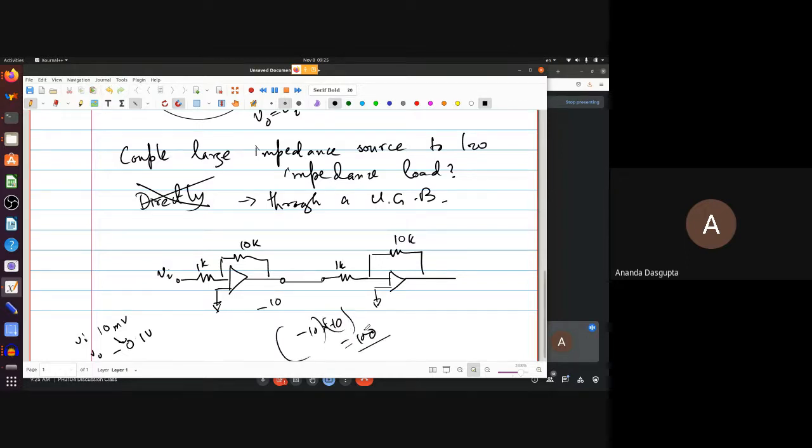Now, this kind of coupling we have to do over and over again various times. The only problem with doing this coupling directly is that the input impedance to this circuit is really not huge. Input impedance to the op-amp may be huge, but as far as the external source is concerned, whatever this source is, in this case another amplifier stage, what it sees here is really not the op-amp directly.